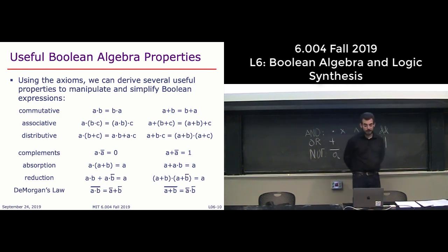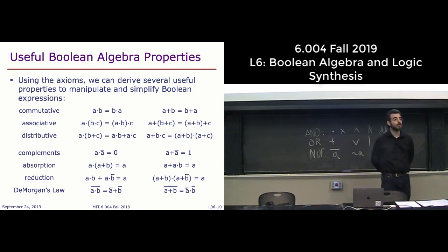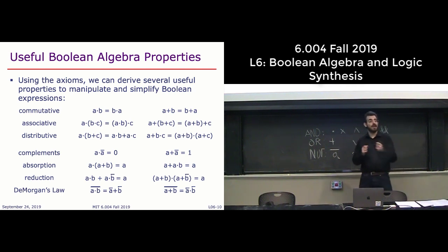And so this associativity is actually very, very helpful to take a sequence or a chain of operations and turn it into a tree, which we will see is much faster to implement in combinational logic. But be careful, because not all the properties are quite the same. So for example, the distributive property, this formula over here for AND should be very familiar, right?